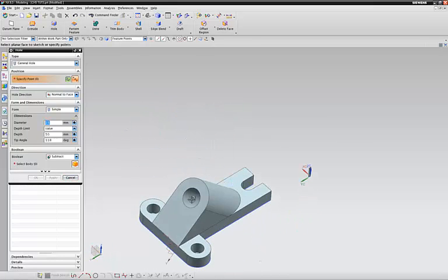Then once you've located your hole where you want, you can even dimension it to a location by using the dimension command. When you're in that sketch, locating surfaces or edges, you're going to subtract it. There's simple, and you can counterbore it, countersink, taper, whatever kind of hole you want. That's what I did for these two holes right here.